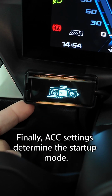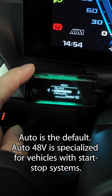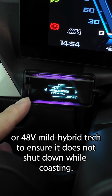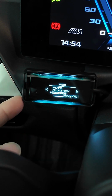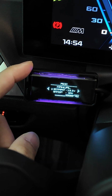Finally, ECC settings determine the startup mode. Auto is the default. Auto 48 volts is specialized for vehicles with start-stop systems or 48 volt mild hybrid tech to ensure it does not shut down while coasting. Next is manual mode for startup failures or special conditions.